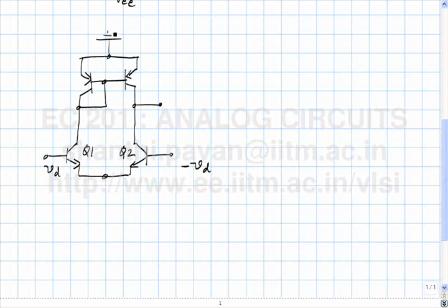Can we actually use half circuit analysis here to simplify our calculations or no? No. Why? The circuit is not symmetric anymore. But thankfully, because of the assumptions I have made, you can actually do it for some part of the circuit. I'll show you how. I replace now every transistor with its incremental equivalent.